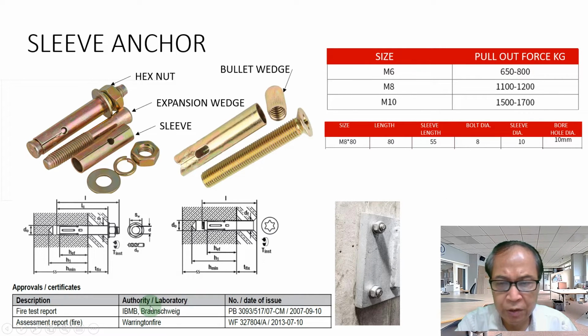For submission to the building authority, we should have some kind of document to support the anchor: certificates for formal submission, laboratory test reports, and certificates. For normal household fitting out, of course, we don't need any certificates.